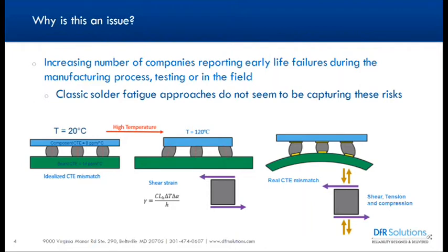The problem with that is that everything we've ever done, all of the modeling we usually do, is correlated to pure shear loading, CTE mismatch between the board and the component. So when you do your test on a board, everything looks okay. And then when you put the board inside of your system, everything breaks.